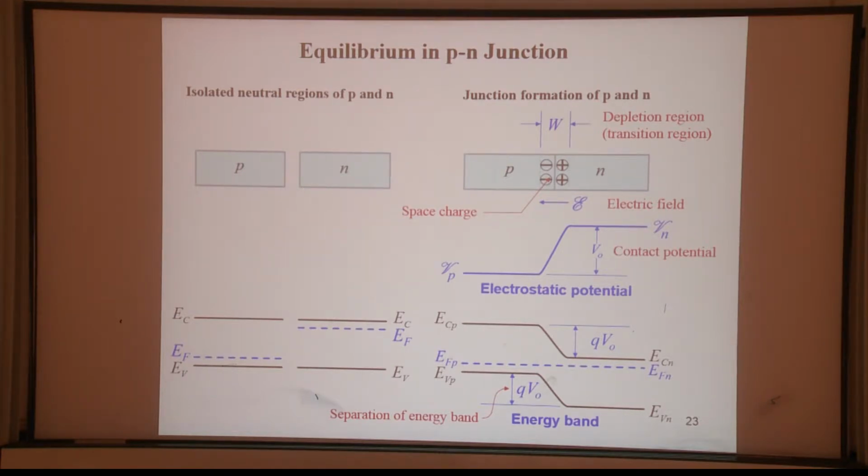When we put them together, the energy band diagram will be something like this. This is very intuitive. You can understand it from the perspective that the Fermi level is the sea level, or water level, of the electron. These two materials have different sea levels, just like land separating two seas. If the seas have two levels, that doesn't matter as long as they are separated.